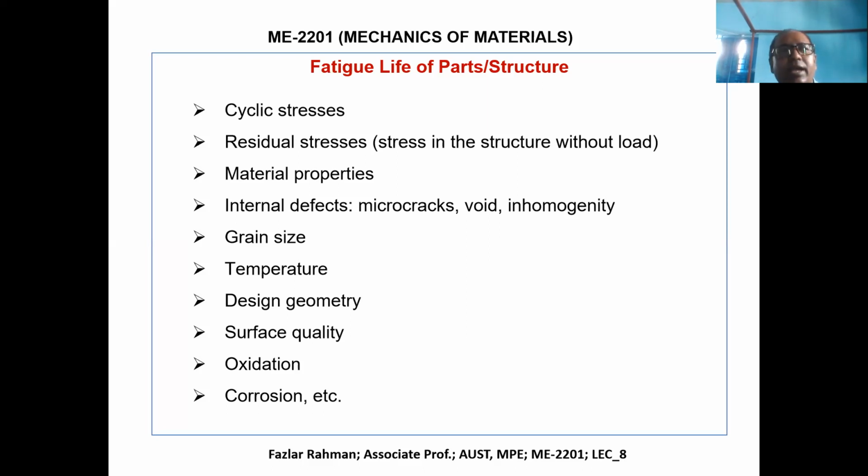And another thing, why does material fail? Material fails because inherently there might be some defect, there might be some crack. If you make it by casting, there might be some void. If you use alloy material, that material might not mix homogeneously. So that's why gradually it develops a crack, and over the years it fails.